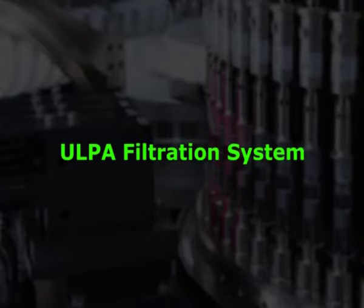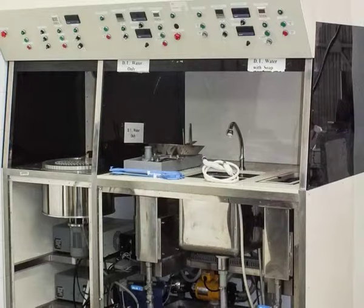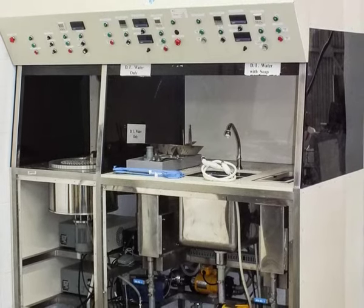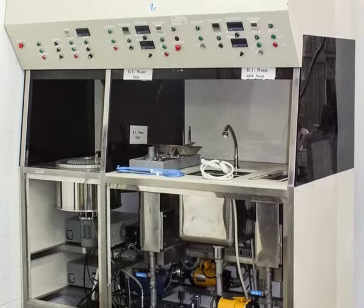ULPA filtration system. ULPA filters typically have an efficiency of more than 99.999% for a size of 0.1 to 0.3 micron filters and are superior to the HEPA filters, as the HEPA filters have an efficiency of 99.97%. The ULPA filters last as long as the conventional HEPA filters and have similar replacement costs. The laminar flow clean benches provide ISO class 3 to class 5 air cleanliness within the work zone as per the ISO on clean benches.